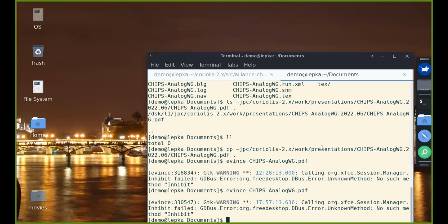I think this is the work of the analog designer to choose the slicing floor plan. This is where we left the analog designer to choose it. It may not be efficient, but in that case, the designer would have to change the slicing tree. Okay, I see. So in your example, you defined the slicing tree in that way, and that was the reason why it looked how it looked. Yes. You just change the slicing tree if you want a better fit to the size of your component, and you will be more compact.